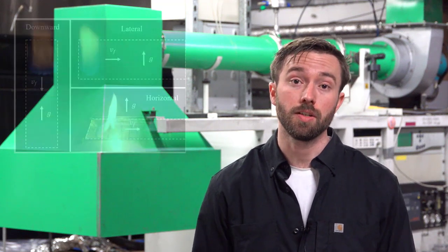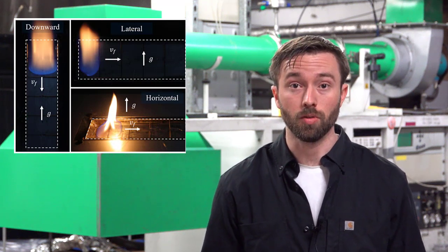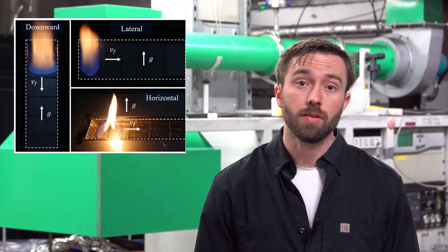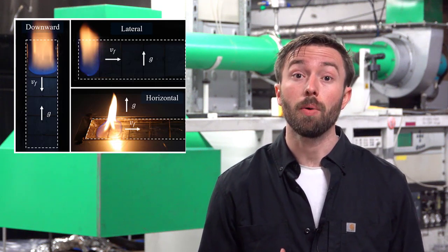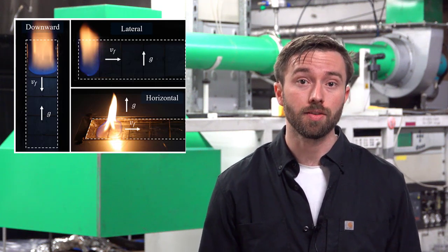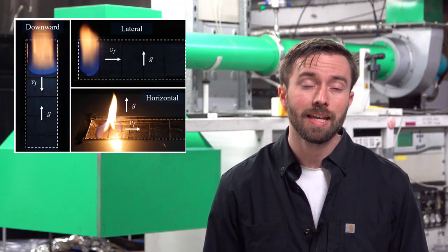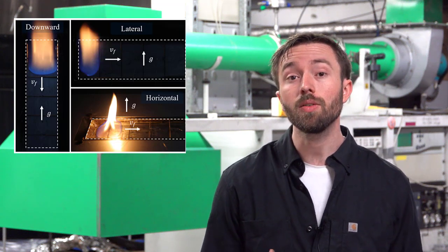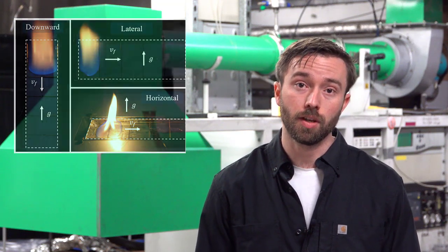Now, the experiments presented here were conducted under a range of different experimental conditions. 3 different sample orientations were used, looking at downward flame spread over a vertical surface, lateral flame spread over a vertical surface, and horizontal spread, similar to a floor type configuration. Now, each of these 3 configurations show a post-flow flame spread, meaning at the leading edge, the flow being entrained along the surface is moving in the opposite direction of flame spread. Yet each of these 3 configurations show distinctly different flame shapes, meaning that the relative contribution between gas and solid phase heat transfer is likely to vary across these 3 different configurations.